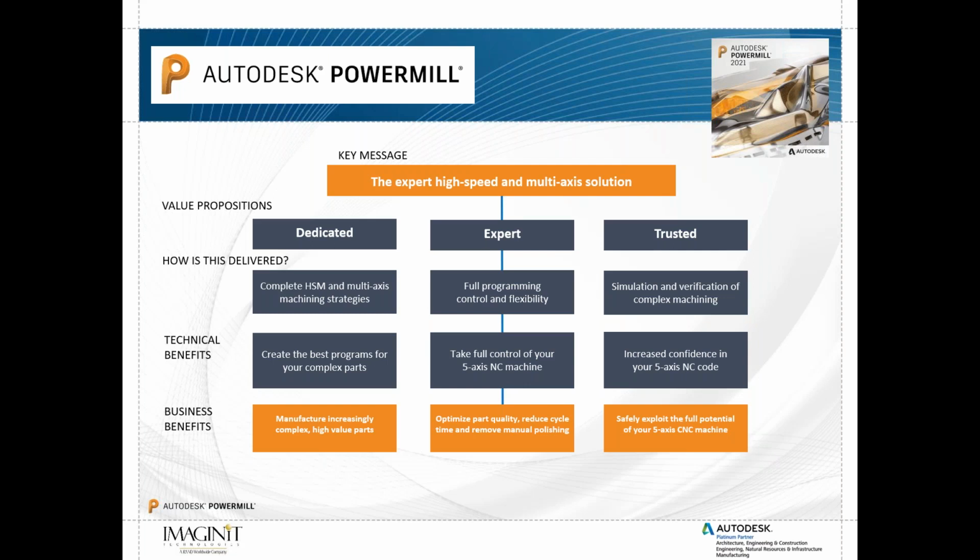Time is money. It's important to save not only on the front end when programming, but also when you're running the toolpath, making sure that you're being as efficient as possible. We also get full programming capability of your 5-axis. Not only can you do simple 5-axis surfacing, you can completely control the indexing of the CNC head or of the table. If you have a 5-axis CNC, you can completely control the position of the tool axis at any point in the toolpath.